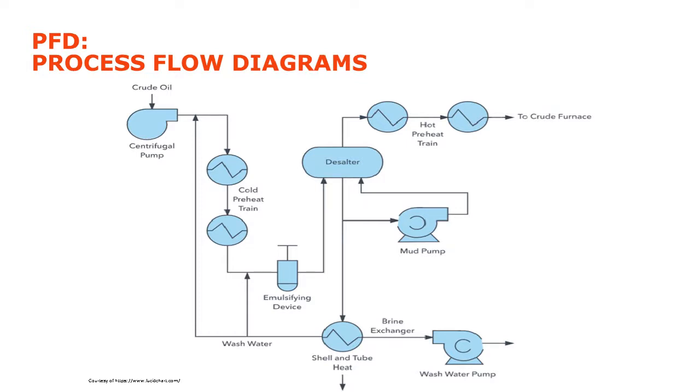This is a PFD. What we see here is the principal process piping, denoted by the lines and arrows, and the major equipment and how they're connected. And you can see eventually what service they serve. This example appears to be crude oil coming in. At the top right, we have crude furnace export. And it just shows the major items, major recirculation systems as well.